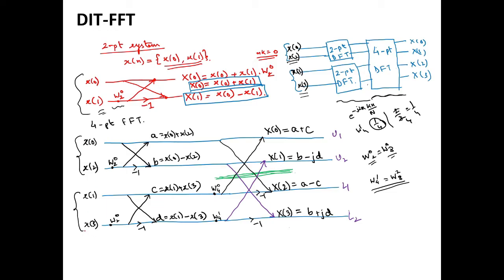Initially, you break down the signal into two parts. You perform the 2-point DFT using this butterfly architecture, right? Once you have done, you get 4 points. Now, in the 4 points, you divide it by the middle line, and you number the lines as 1, 2 in the same order. Top one, 1, 2, second one, 1, 2. Okay. Now connections would flow from 1 to 1 in either of the directions, and the top one will not have any twiddle factor because in this butterfly architecture, the top part does not have any twiddle factor. Only the lower line from where the signal flows would have the twiddle factor. So the lower lines will be having the twiddle factors.